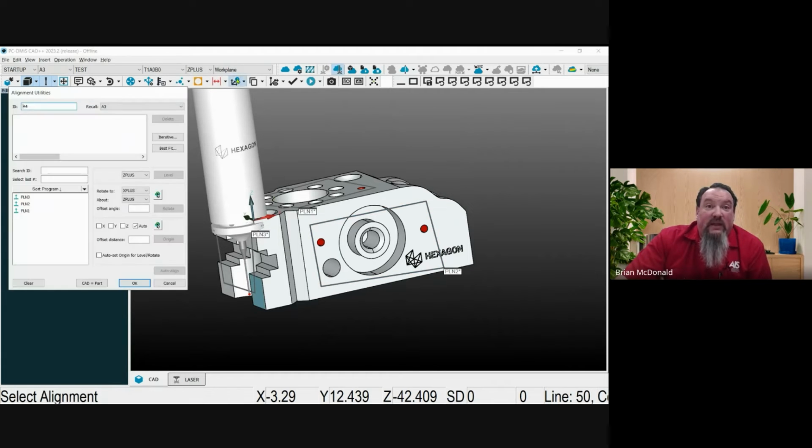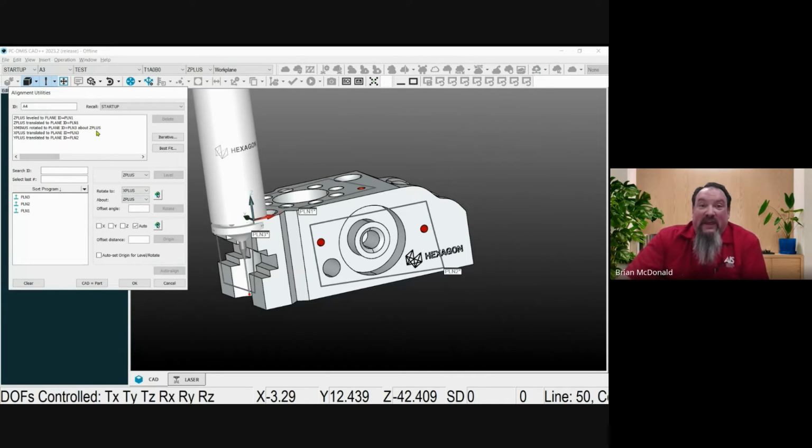If we go in and take another one, but I'm going to select plane 3 second, and I hit that auto align, now it's rotated to plane 3. It's doing it right. If you're using this auto align button, make sure you are selecting those in the correct order. That's one of the biggest things that I had trouble with when I started, and one of the things we see is people might grab those in the wrong order. In this case, this sort is backwards for me from the way I see it, so I would have selected the wrong plane first.